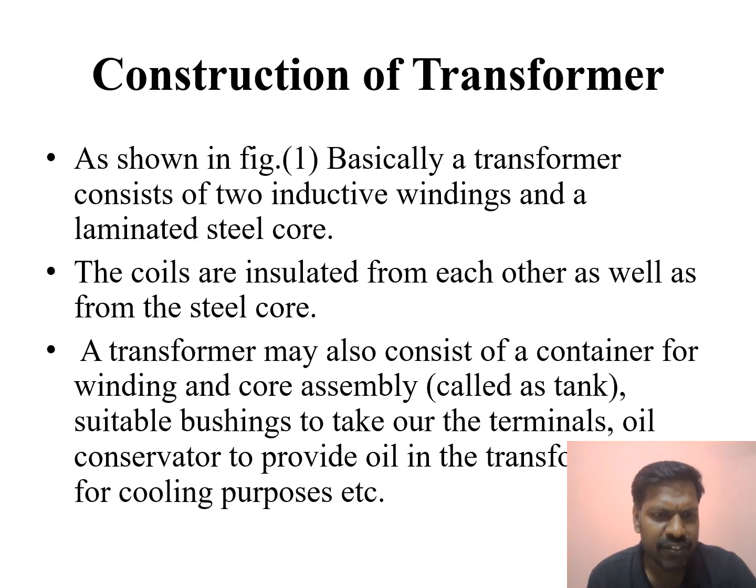Practically, if we connect the transformer to DC, the primary winding behaves almost like a low resistance coil, causing very high current and possible overheating or damage to the core and winding.